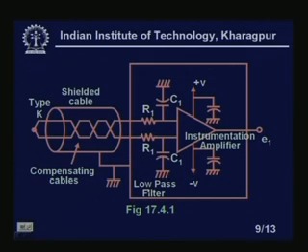Now see that for cold junction compensation we use a thermistor. Thermistor being a nonlinear device, we need to use linearization techniques. This is then passed through an amplifier to make the sensitivities of these two circuits identical, so that it will take care of ambient temperature fluctuations or variation.